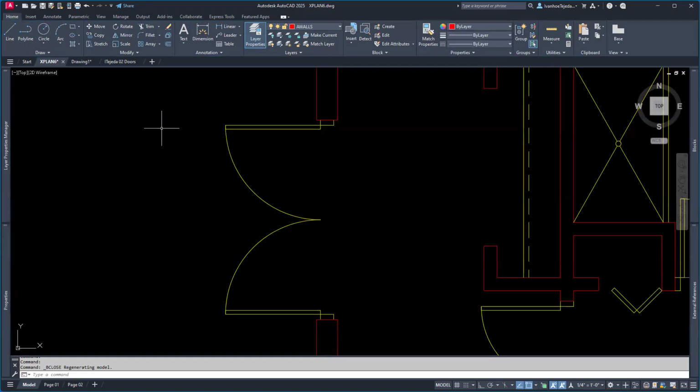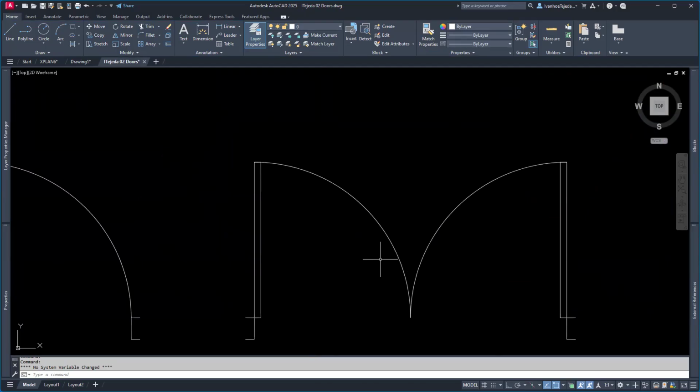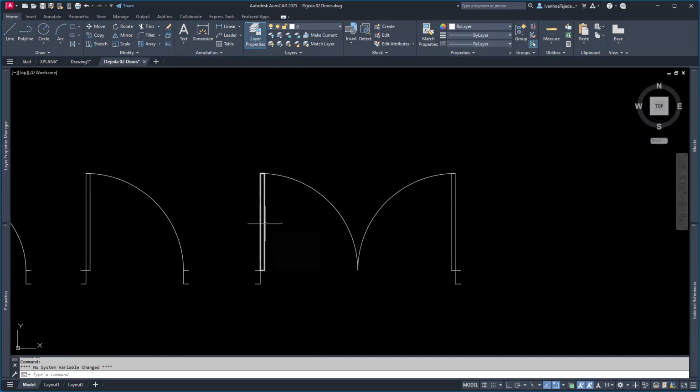And then I opened up my doors drawing file here, and I want to now take this block, or actually I don't have it as a block, so let me go ahead and from scratch give this a go. And I do have these as polylines. Okay, that's okay. All good, that's a polyline, great. So time to make my block.